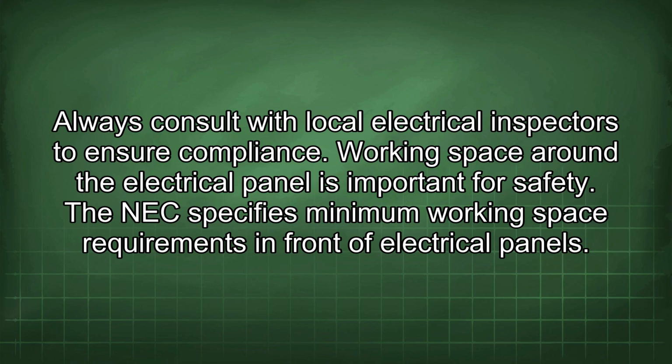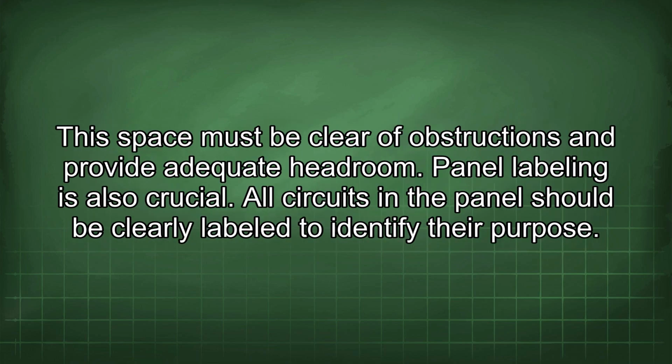Working space around the electrical panel is important for safety. The NEC specifies minimum working space requirements in front of electrical panels. This space must be clear of obstructions and provide adequate headroom.